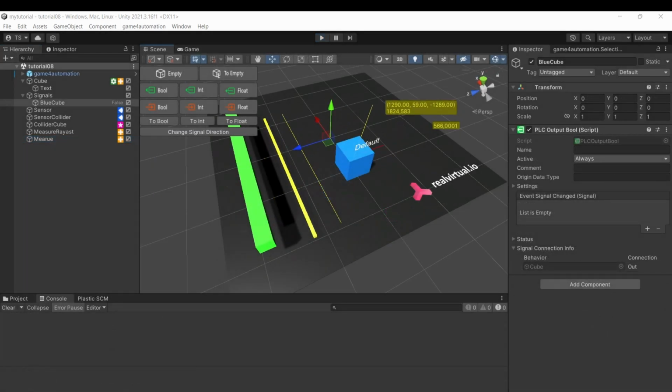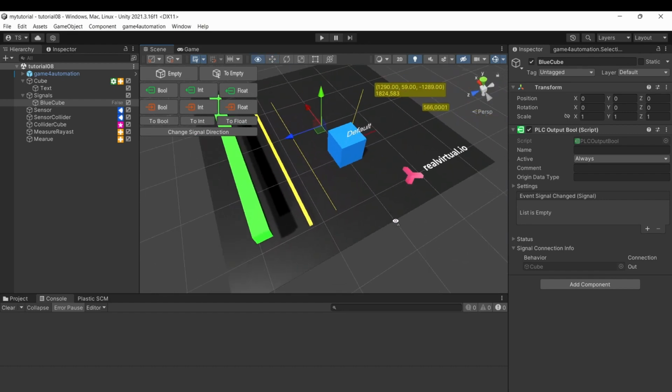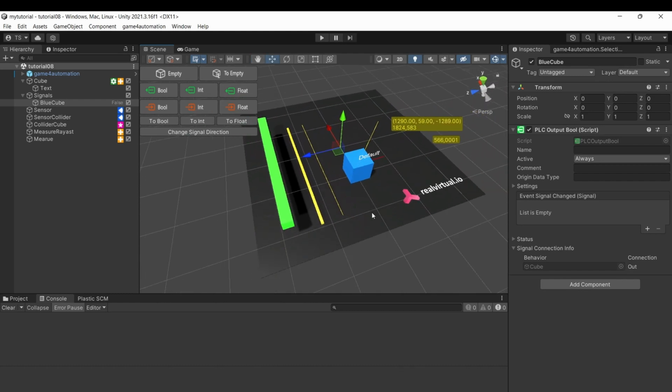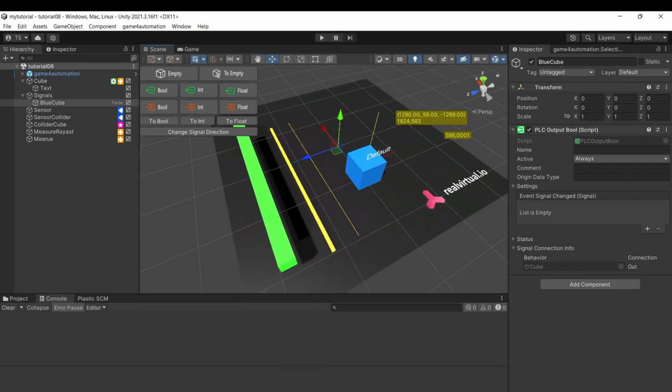That's all for this tutorial. Maybe not so nice 3D components and movements, but the layer and sensor system is something very important. And in a lot of support cases, the issue is just that the layers are not defined on the components as they should be. So if things are not colliding, please always take care about the layer settings on your movable components, on your transport surfaces, and on your sensors.